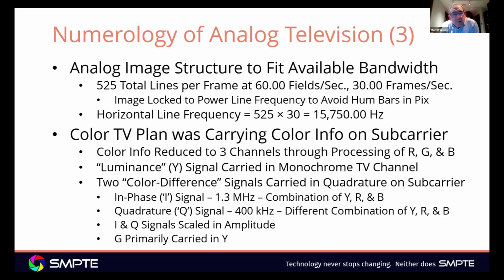And the horizontal line frequency, since we had 30 frames per second and 525 total lines, that led to 15.75 kilohertz or 15,750 hertz of line rate, which was an important number as we go forward into thinking about the color situation. Both of those really are.